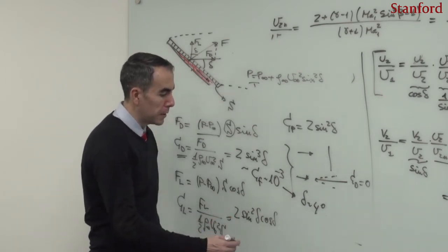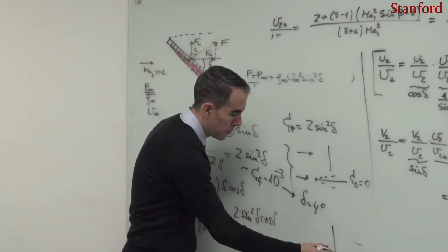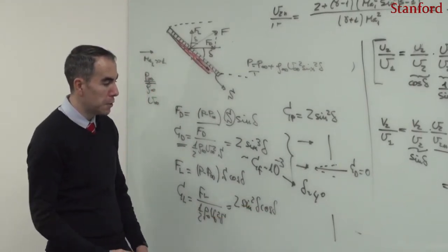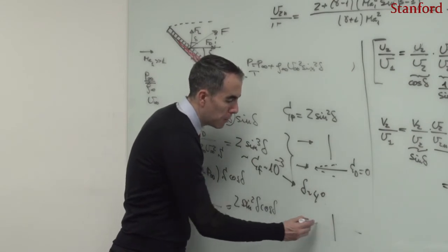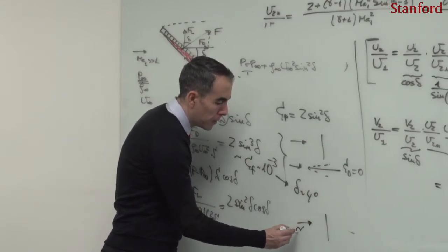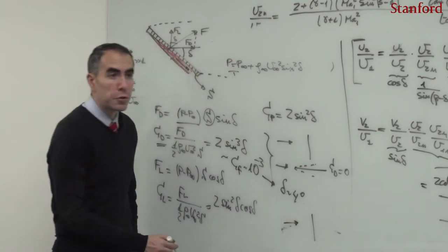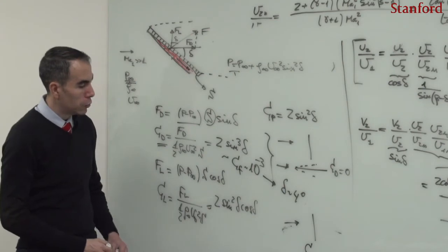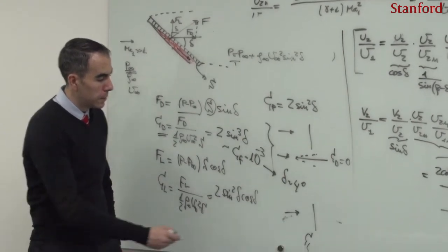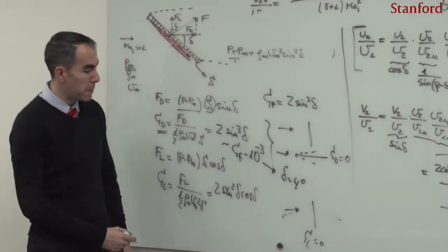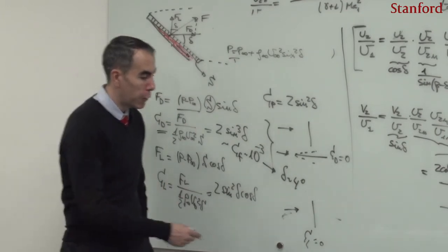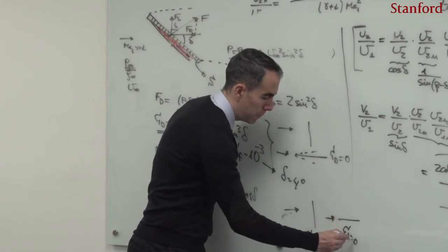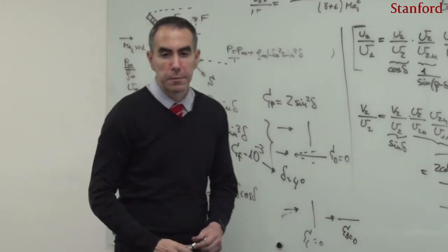when the plate is vertical, right, then the cosine of pi halves is 0, and as a result, when the plate is normal to the stream, the lift force is 0 according to this expression. And also, when the plate is horizontal, the lift force becomes 0 according to this theory. And we can see this thing in the chart.